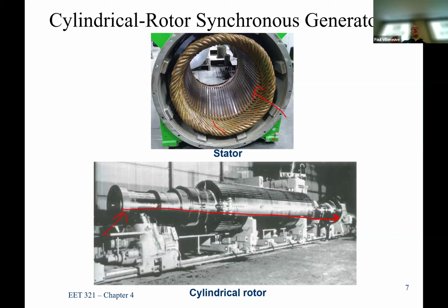Sometimes on big generators, because if you have a big generator circuit breaker pulling 10,000 amps, you just physically need a lot of room. So sometimes they use SF6 because they don't want the breaker to be the size of a house. So they might use that, but SF6 is pretty limited for that. One of the other things about these rotors is they're really long. What happens when you suspend something over here and over here and it's really long?